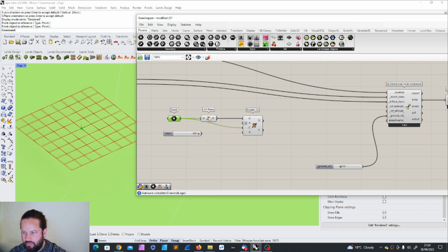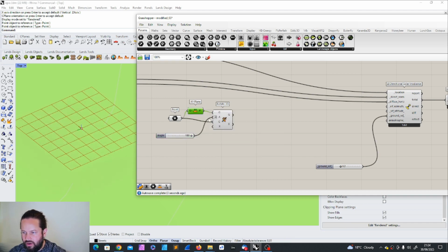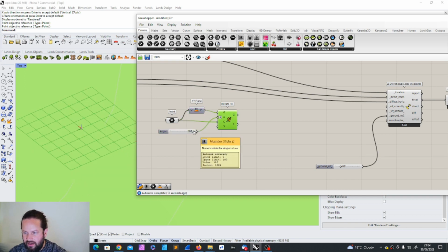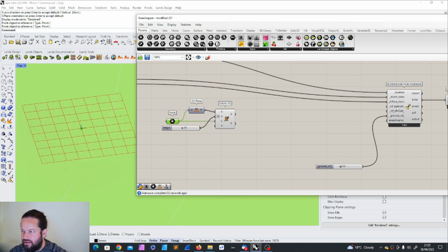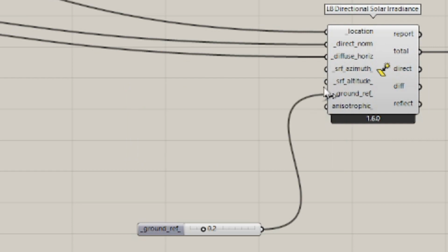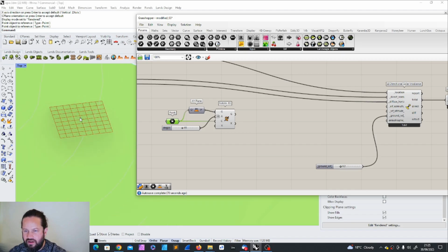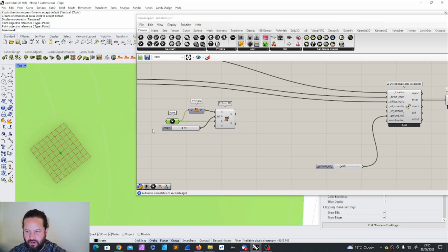We also need to make sure that our center point is placed, so that the point in the middle is the center point of the rotation as well. And then we can use this here. I'm turning off the original plane, so we only see the new plane. And now the problem is it rotates in the opposite direction. As you can see here, north is still correct. Then I rotate. Here it says 90 is east, and south is 180. As you can see, that's the first problem. This is north, but then it rotates against the clock.